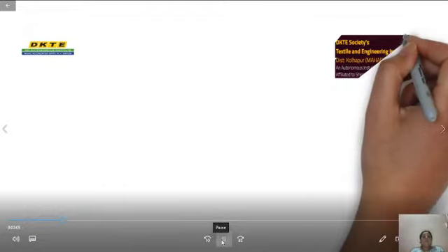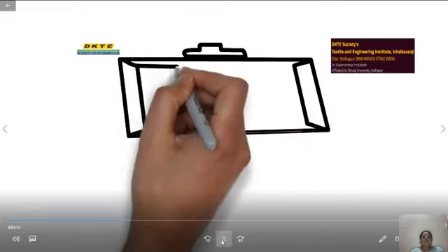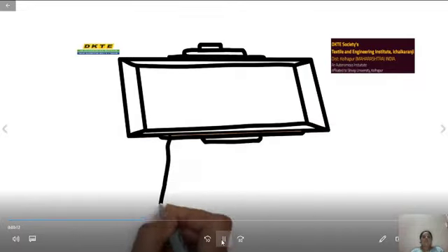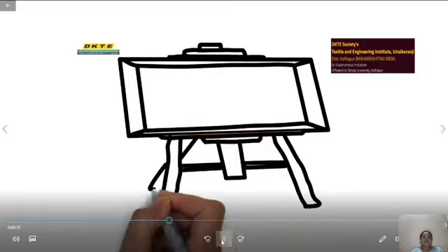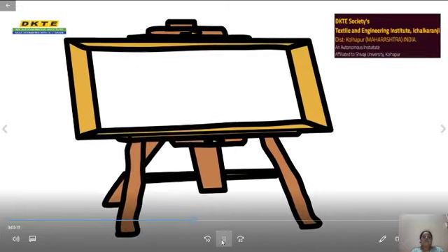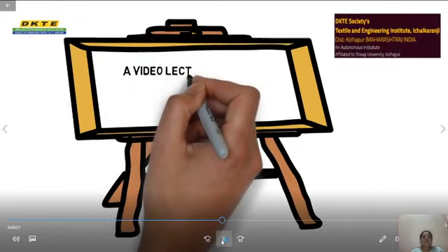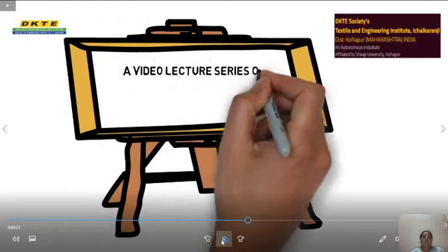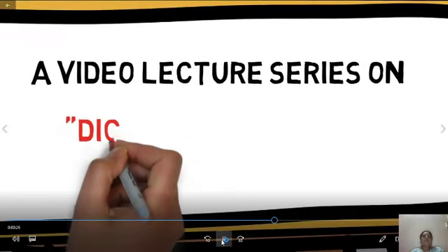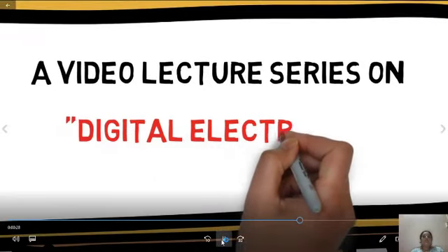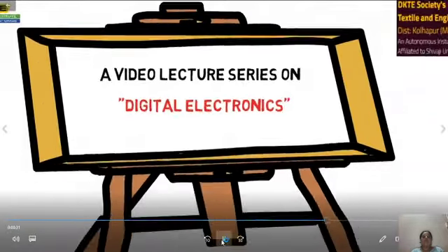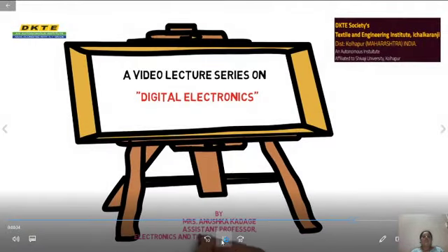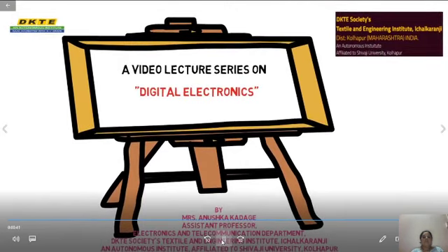In the previous lecture we went through the process of designing the combinational circuit. Then we completed concepts like half adder, full adder, half subtractor and full subtractor, wherein for each combinational circuit we prepared the truth table. From the truth table, the K-map building was completed, and based on the reduction obtained by using the K-map, we defined the logical circuit for that combinational circuit.